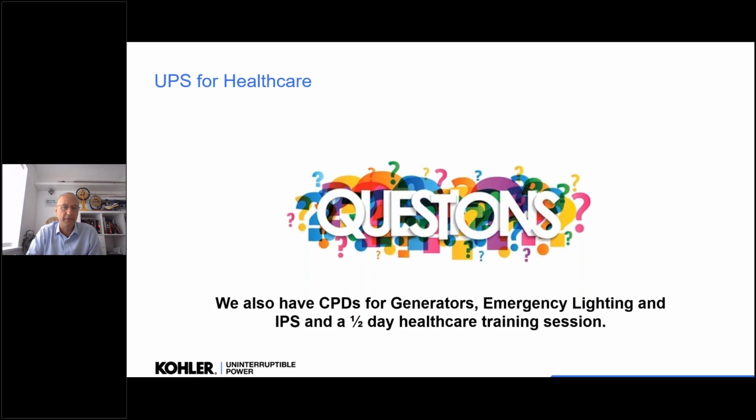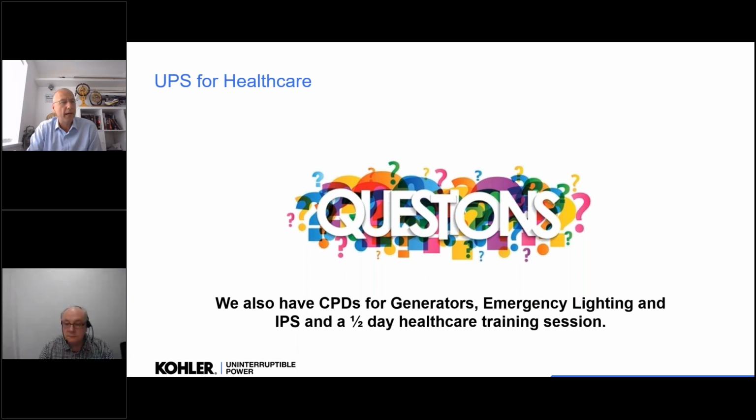the advantages of lithium are kind of taken away, because the advantage of lithium is the efficiency at very short, fast discharges. When it comes to 1 hour, 3 hour batteries, the benefits of lithium are reduced, and typically due to the cost of the lithium and the fact that guidance talks about having VRLA batteries, we're not seeing lithiums being put in hospitals.